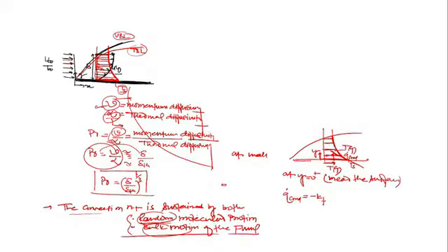Whatever thickness is there, the solid is isothermal, my dear student. The temperature is constant, and no heat transfer takes place in the solid. Yes, that's why we should write the thermal conductivity of the fluid only. Is this clear? Minus k of f, that's very important. To create confusion, they may also give you k of solid, but there is no role of k of solid, only k of fluid. So minus kf into dT upon dy at y equal to 0. Clear? 0 plus or 0, whatever you like. This is the heat transfer by conduction.